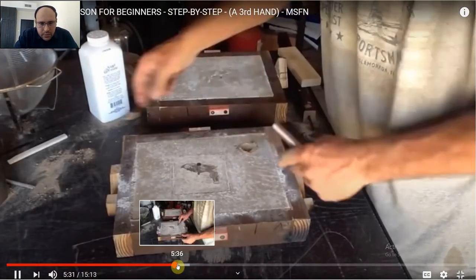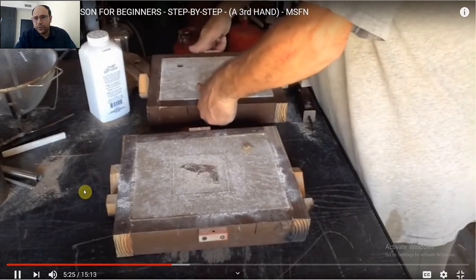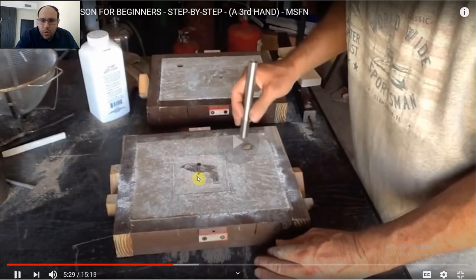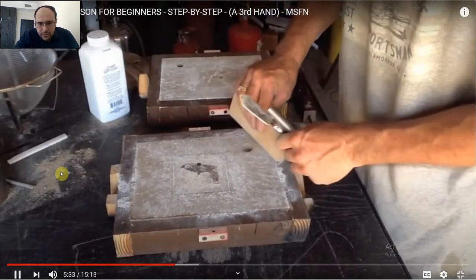Area around where the sprue comes in. Now he's gonna open again the 2 halves of the flask or the mold. So as you can see, he's trying to get the button. The button is already formed here. It is already on the top. It is trapped inside the sand, yes. And he's putting a little screw that he made before so he can easily get the button out from the sand. Where the screw comes in, that's where you pour the metal.